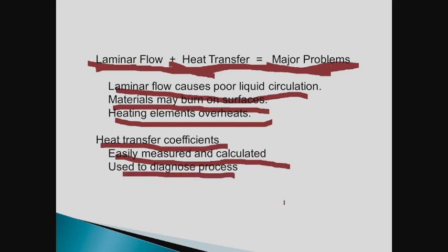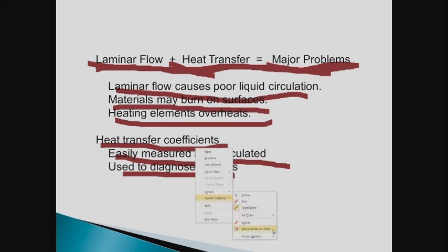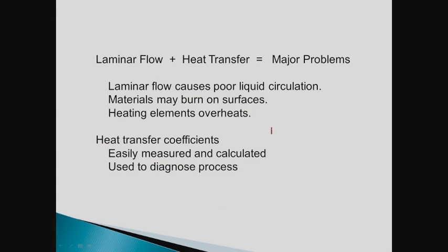And it can be used as a diagnostic tool. Obviously, it will tell you perhaps when to clean, right? When to clean. Let's go over here. So what happens is you have the heat transfer coefficient, or say overall heat transfer coefficient. That's the U times the area. And down here you have time, basically.